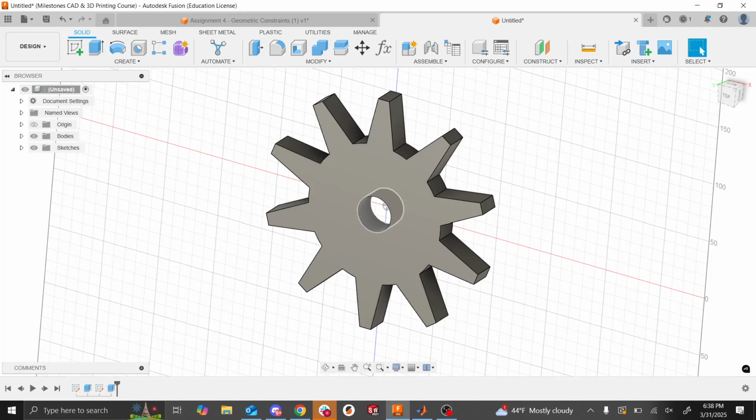It just knows that there's some area that doesn't have material there. So it may not select a drill bit, which you might want to use for this case, and it might select another tool to cut this hole out. So to give the most information possible, you want to avoid doing this if you're making circular holes, right? Obviously, if you have some geometry that has to be specific, please do this.